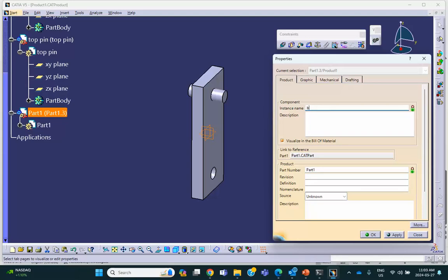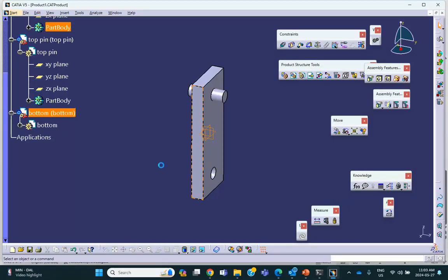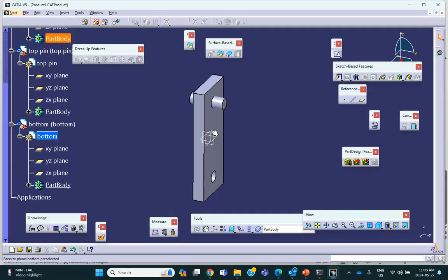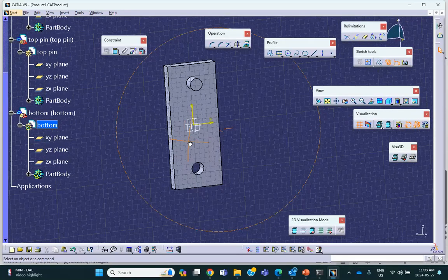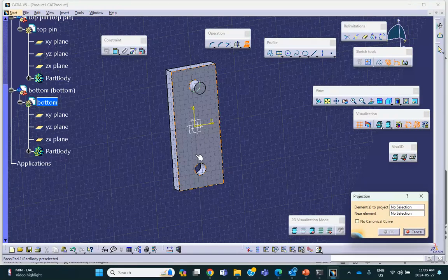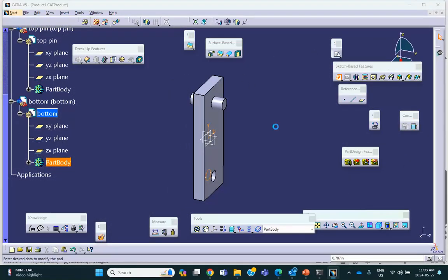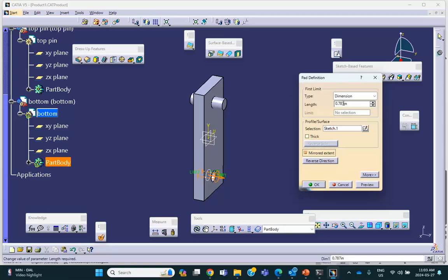This is crazy because they're identical. You should not waste resources like this, but that's fine. Or you can do instantiation if you know what I mean. Otherwise, just go make it. Double click on it. On that vertical plane once again. Select or sketch. Project the bottom circle. Good. Exit. Add it. Mirror extend by 1.5.